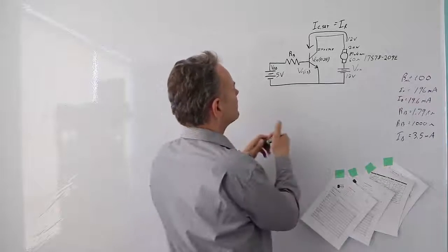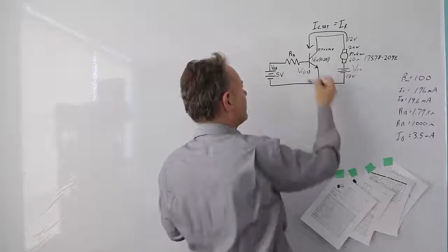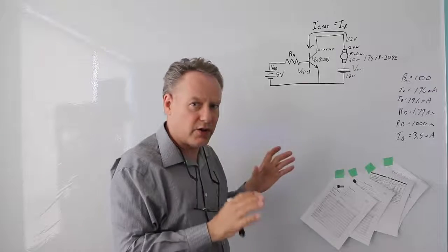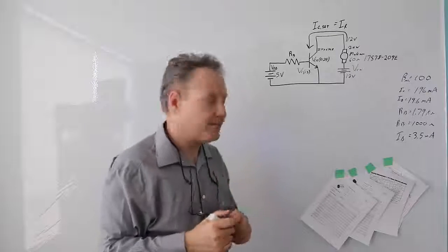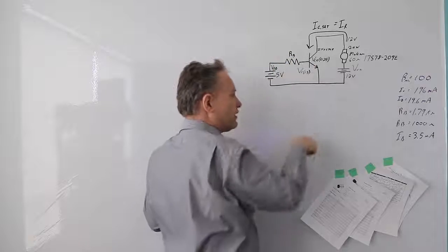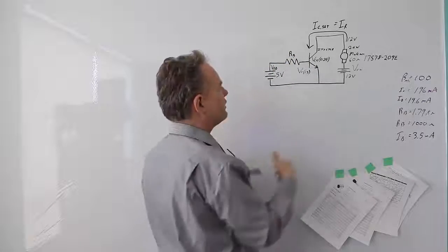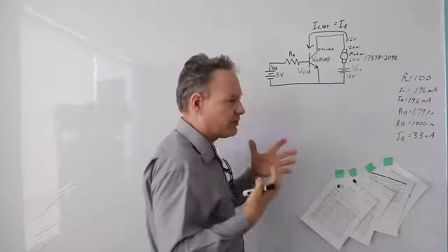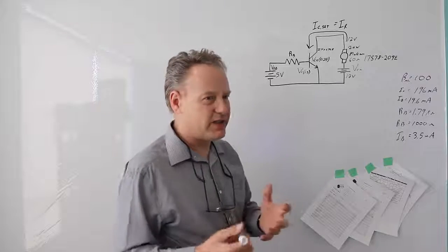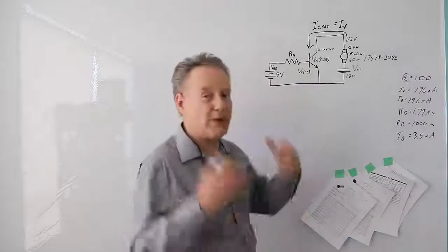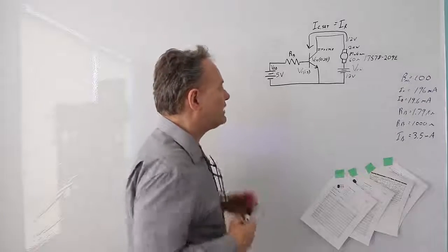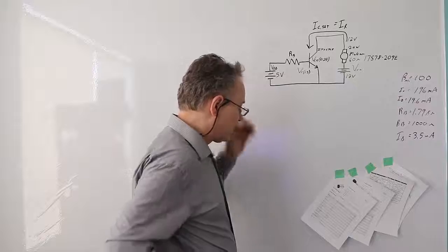So what we have here is this current that's going through the motor and through the BJT, and when we use it as a switch, we know the BJT is going to be working in saturation. To fully saturate it, we've got this base current going through here, and it's going to be balanced using the gain. The gain is 100. Essentially, the current that goes through here has to be 1/100th of the current going through the collector. Good. So let's actually walk through the steps, but first let's just take a look at what's going on here.